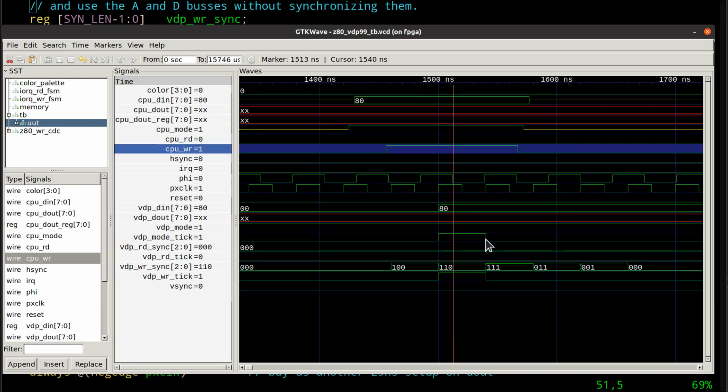Because the whole point of stealing the copy early is because it could go away by the time over here when the next clock comes along, which would be the one we use if we didn't see this here, because that's a close call. It could have seen a 0 and saw the 1 here, and the whole thing would then take place over these 3, at which point I'm in trouble, okay? So I'm going to steal a copy of what's on the data bus here.